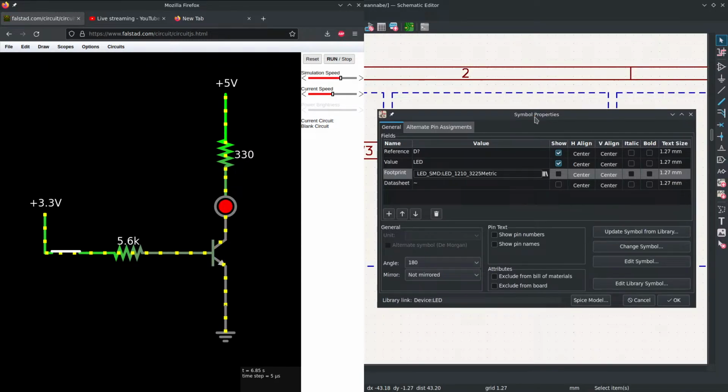Why? Because one disadvantage to the hand solder version is that it has a bigger pad, so when I've tried to solder LEDs, they'll solder and make a good connection but be kind of crooked. That doesn't matter if it's a resistor, but if it's an LED, you'll notice if it's crooked. So I'm not going to do the hand solder on those, even though it's harder to solder.